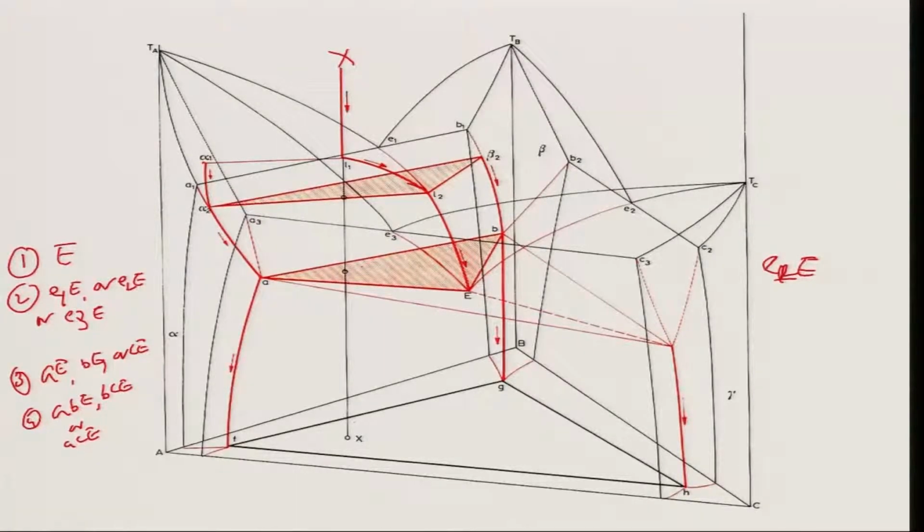This is the thing, let me write down again, it is sitting on that. Because it is sitting on this, it has to crystallize both alpha and beta, because this is the eutectic, U1, a eutectic corresponding to binary AB producing alpha plus beta. Therefore, the valley connecting U1 to E will lead to crystallization of both alpha and beta, and here the same thing will happen: alpha of composition alpha 2 and beta corresponding to beta 2 will crystallize from liquid.